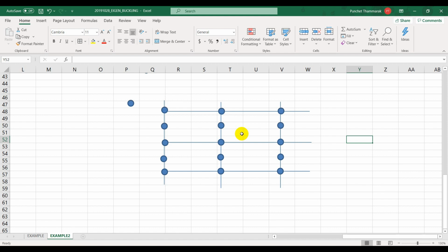The benefit might be just a little bit. You don't get the full benefit because you don't allow this degree of freedom to be in your calculation, right? If you look at the frame structure, axial load in the beam might not be so high in general, but the axial load in the column is large, and without the discretization over here to pick up the large deformation which is going to be at the middle of the column, then your system is not sensitive to the P delta effect, and that's the waste.